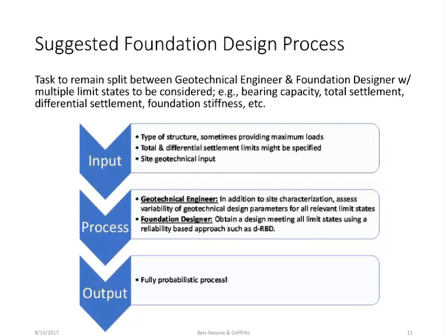What I'm suggesting is a fully probabilistic method. The task is still split between the geotech engineer and the foundation designer. They still start with some type of structure, the limited information we typically have, and the criteria for serviceability limit states. But now the focus of the geotech engineer should be to assess the variability of the geotechnical design parameters.